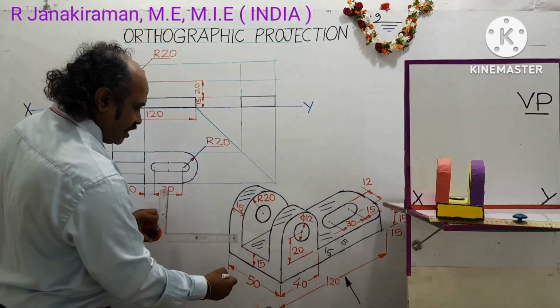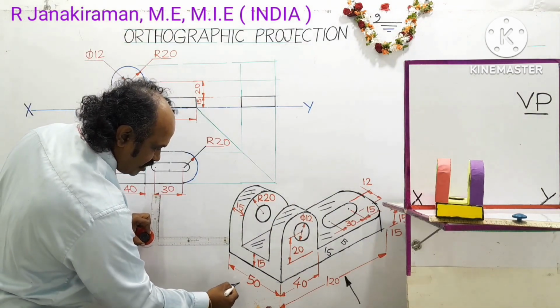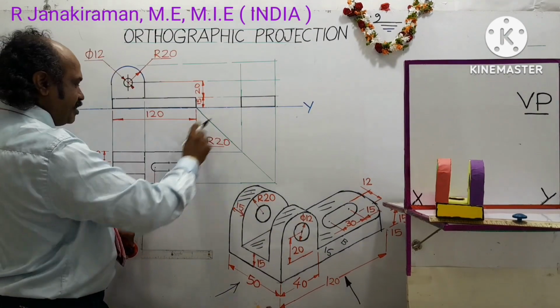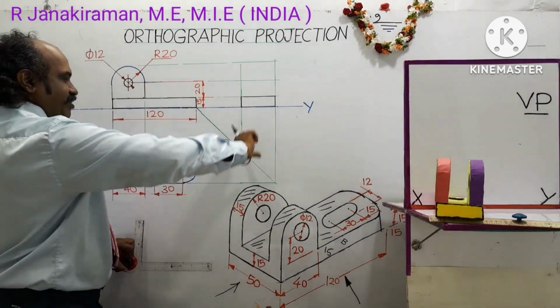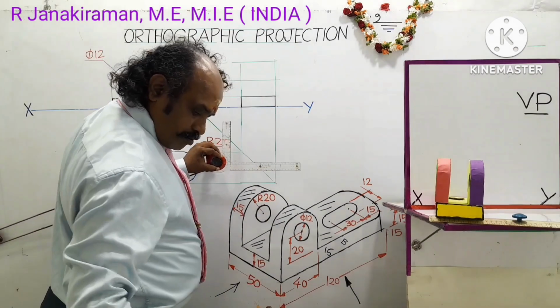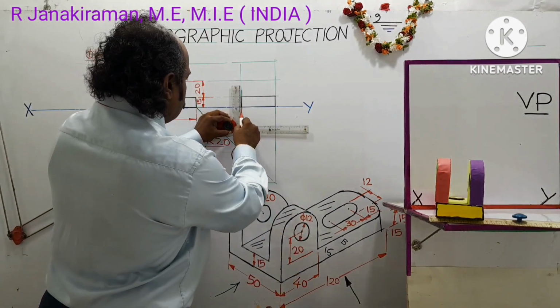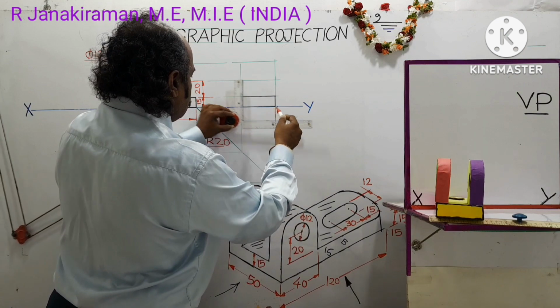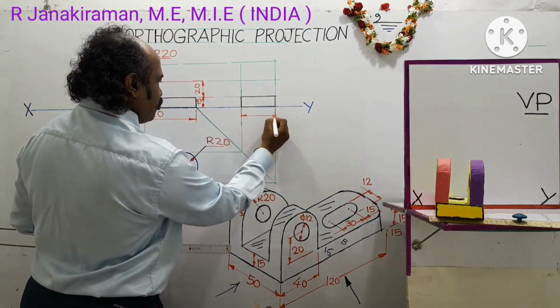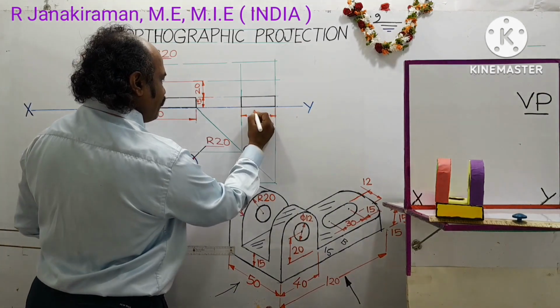So looking in this direction, called the left side view direction, the observer can see the base part, base breadth 50 mm. You can see that this is the base, 50 mm. Let us dimension this. Draw a dimension line, put two narrow arrowheads on both the ends of the line, and write 50.